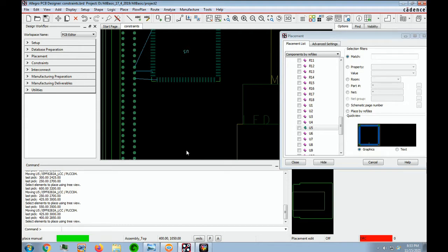You might notice that as you are interactively placing components, power and ground nets are not rat nested. A no-rat property is automatically added to the power and ground nets when the logic netlist is read into the database. This is done as a visual aid, assuming that these nets will automatically be routed to their respective internal planes. It is helpful to have these nets in a different color so that you know where to place the discrete components that are often assigned to those nets.